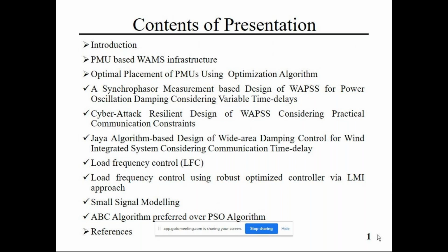But the more important point is that there are a lot of nonlinearities, different saturations, dead bands, and so on, in contrast to the classical power network, in the converter dominated network with a lot of power electronics converters, your SVC, your FACTS devices, different types of loads, and its inertia response. It is very complicated to realize unless a specific approach is adopted to get the expected response.